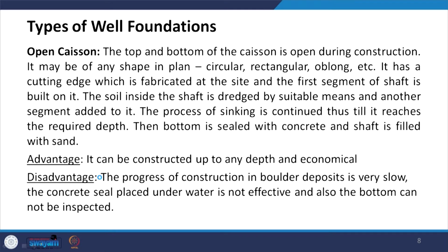So, what are the advantages of this? It can be constructed up to any depth and is economical. While the disadvantage is that the progress of construction in boulder deposit is very slow. If you have hard rock strata, then it will be difficult to cut, and this is slow. The concrete seal placed underwater is not effective, and also the bottom cannot be inspected. So, these are the issues with open caissons.